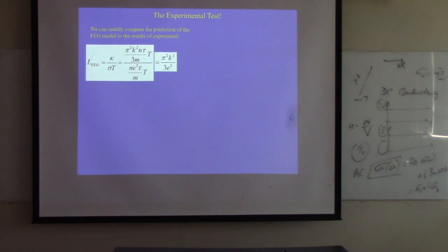To make ZT large, what do you have to do? You have to increase sigma and decrease kappa, right? But we know this ratio is constant, so there's nothing you can do there, because if you try to increase one, you can never decrease the other. But people found a way to do that. So what can you do?